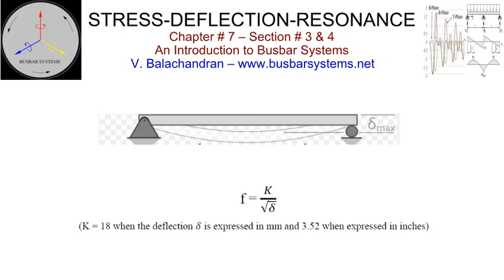On a short circuit, the force will have an oscillating frequency corresponding to the system frequency and double the system frequency. It will be 50 and 100 cycles per second for a 50 Hz system. It will be 60 and 120 cycles per second for a 60 Hz system. Any beam supported at its end will have a natural frequency of vibration which is based on its moment of inertia, span, and modulus of elasticity.